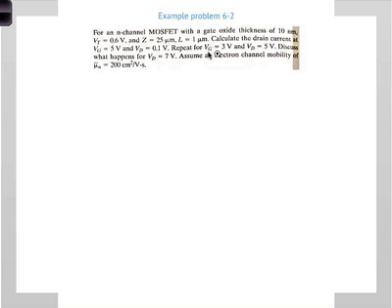You're still above threshold. 3 minus 0.6 is 2.4. It's still in the linear region, and so on and so forth. Now these two are straightforward. Actually, this part, let's think about that a second. When VG is 3 volts, it's above threshold, so the channel exists.